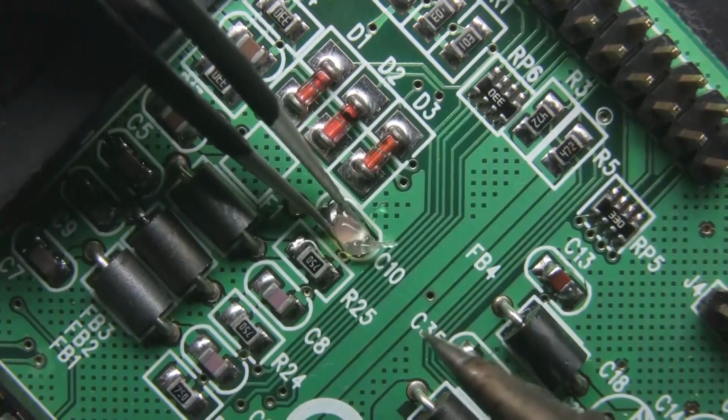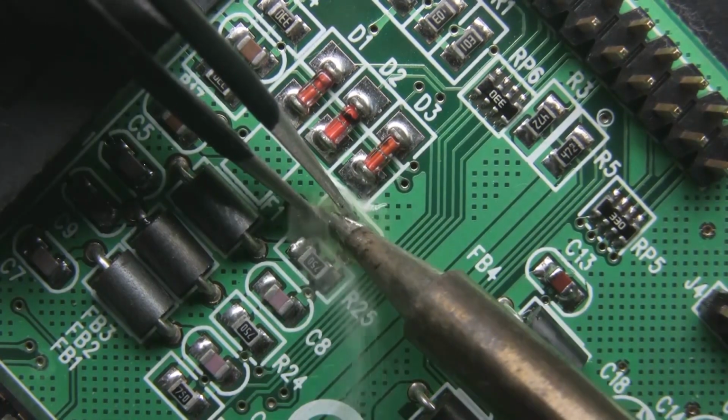As we know, in modern semiconductor devices like thyristors, MOSFETs or IGBTs, a gate pulse is required. Specifically, when I talk about a thyristor, a gate pulse is required to switch on the thyristor. The gate pulse or gate signal is provided by a circuit which is called a firing circuit. The purpose of the firing circuit is to give pulses to the firing terminals, which is the gate in modern semiconductor devices.